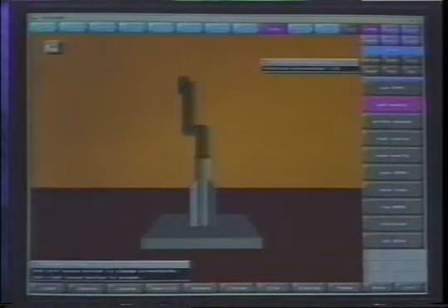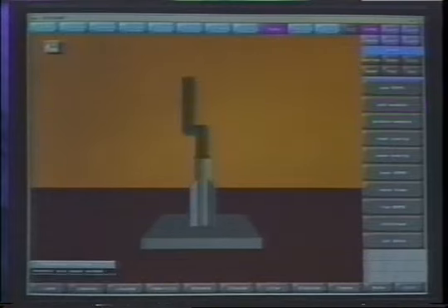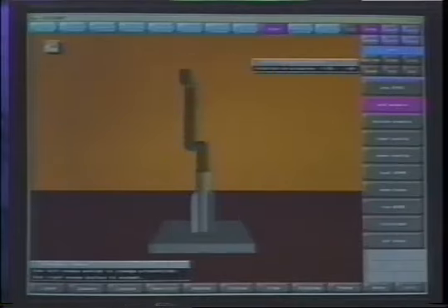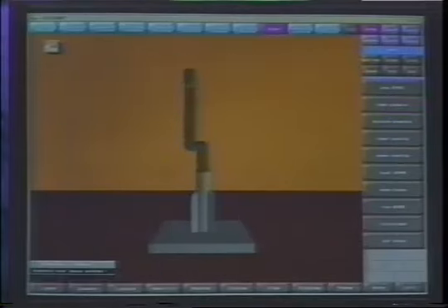To evaluate new manipulator configurations quickly and safely, we have built an RMMS simulator using Telegrip simulation software. The user can build an RMMS configuration interactively by selecting modules from a database and mounting the modules in the appropriate orientation. The simulation runs on a Silicon Graphics workstation which is connected to the real-time control hardware. This allows us to simulate a task while running the control software on the real-time processor used to control the physical RMMS.